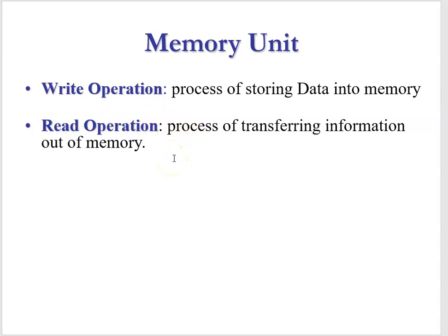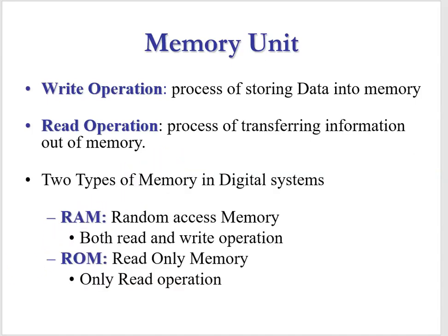If we have a flip-flop or a register, once that data is in the register, it's available at the output of the register. That's not quite true for a memory unit, so we have a specific operation for that. Instead of talking about loading memory, we talk about writing it, and then we also talk about reading memory. And we consider it a unit of memory.